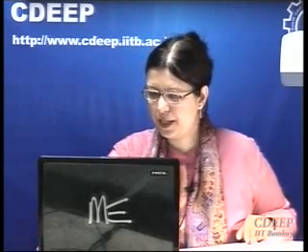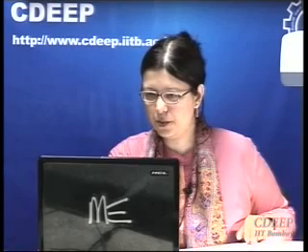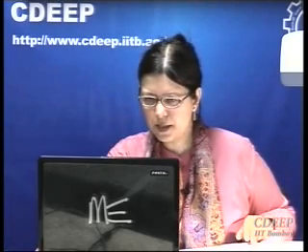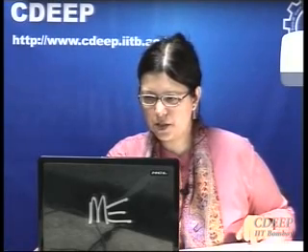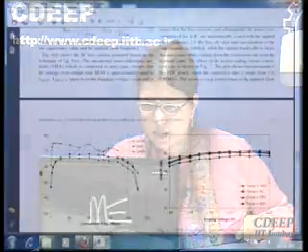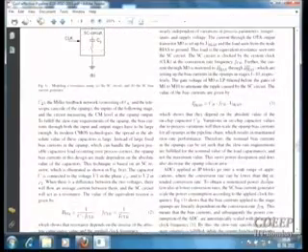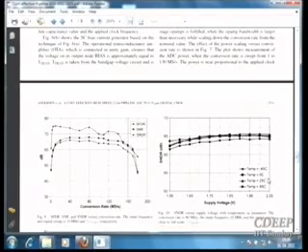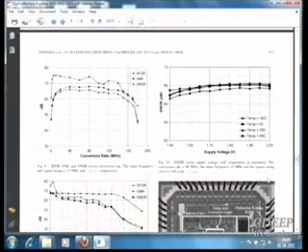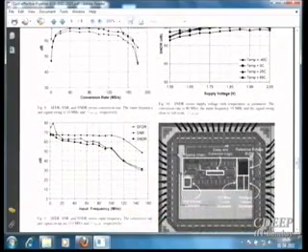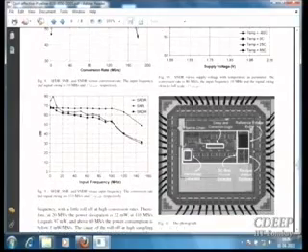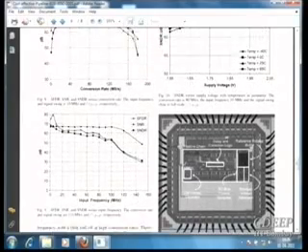Okay, before going to that, just one thing I mentioned, we need to add to our, this is also simple, you will see this switching arrangement to reduce on resistance. This is the switching bias generator. Okay, interesting. INL, DNL plots are not given, but SFDR, SNR and SNDR are given, again versus input frequency and versus conversion rate for a given input frequency.